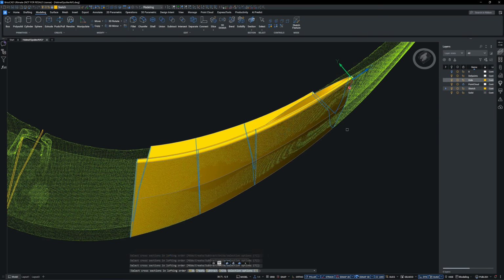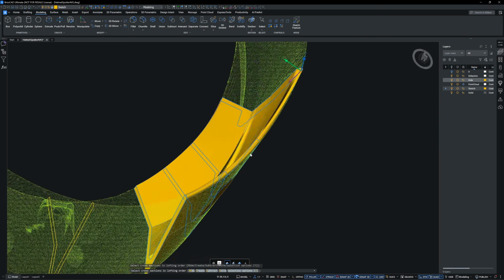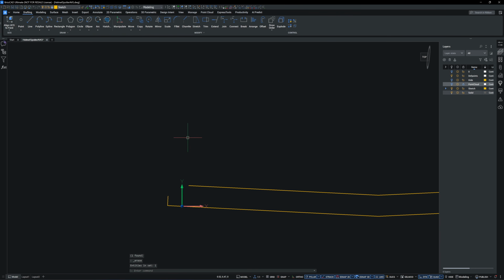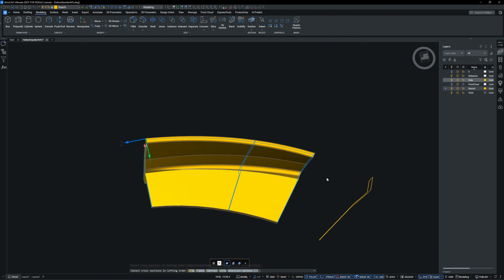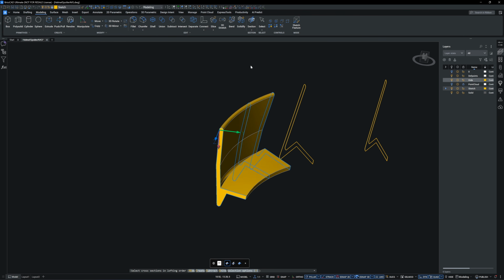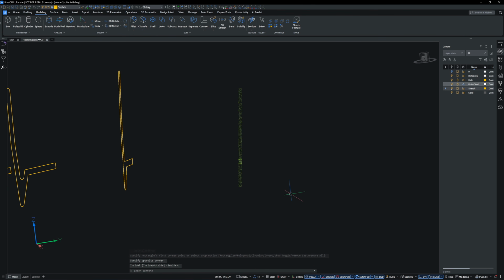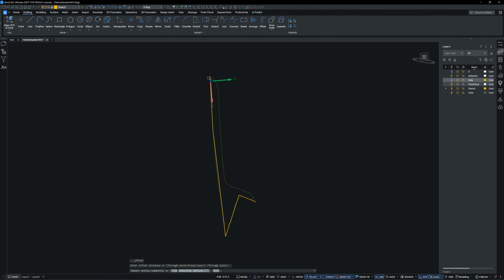The loft profile differs too much. The previous profile has a round top edge, so the next one also needs to include that round edge. Otherwise, you have to force the shape with a guide rail. Here I'm creating another profile.